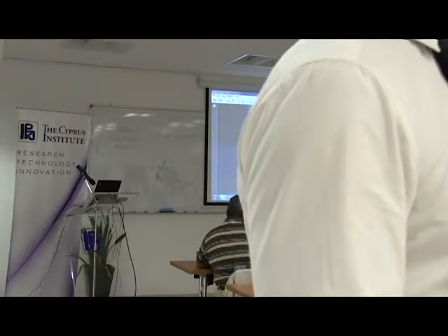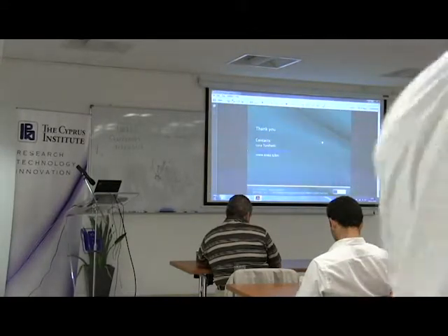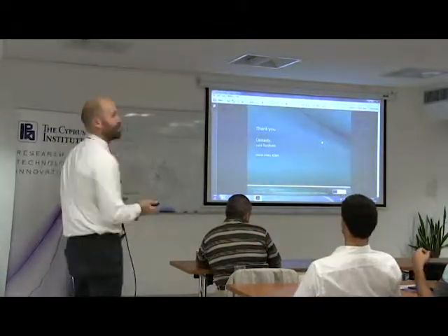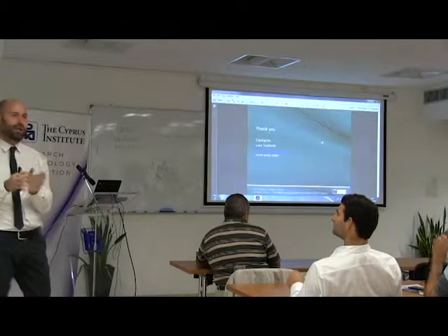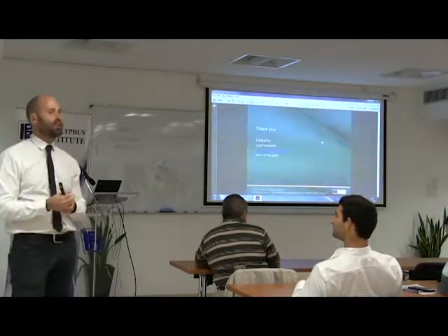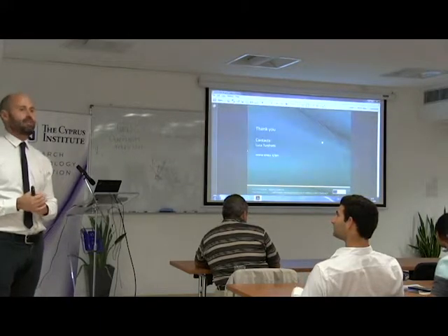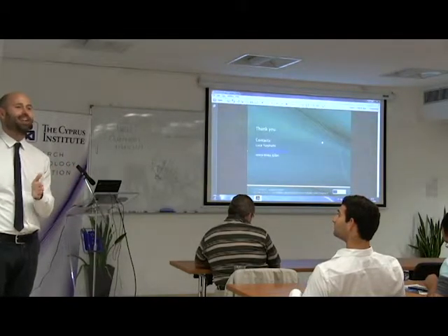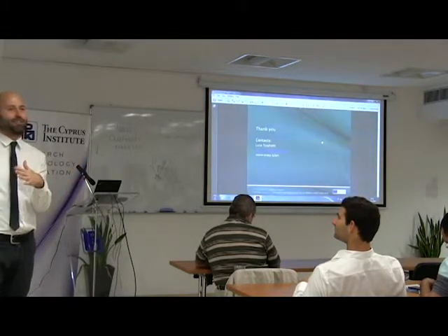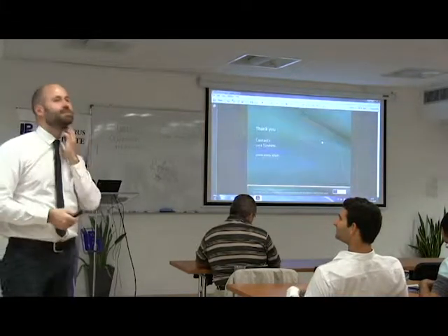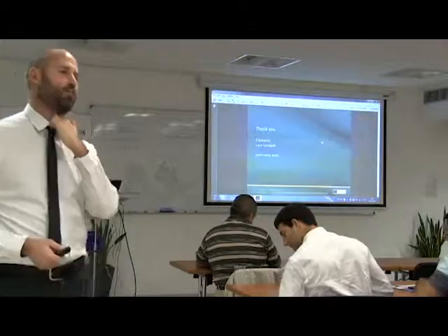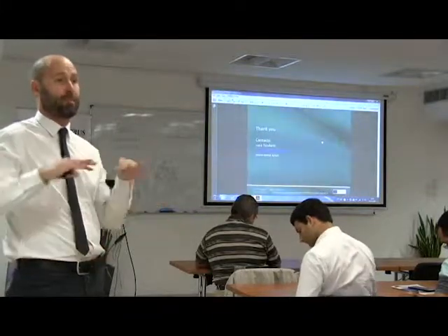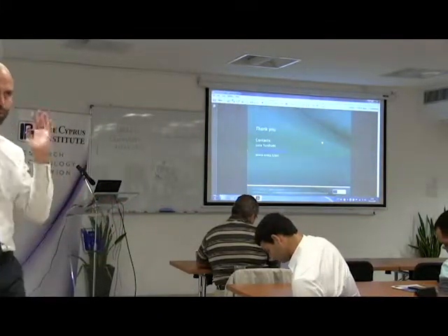Did you see both approaches? So from water and from methanol. The one from methanol, the name of the project you probably know because the coordinator was Alberto. It's commonly where CO stands for compact. Compact, multi-fuel. I know that technology is suitable to be built at very small scales. The problem is that if you want to power it with solar energy, the limiting part is probably the solar field. So there is no limitation on the chemical side. Of course, the economies of scale are important, but from a technological point of view, it is scalable and very modular because it's a shell and tube configuration, which is very modular by design.